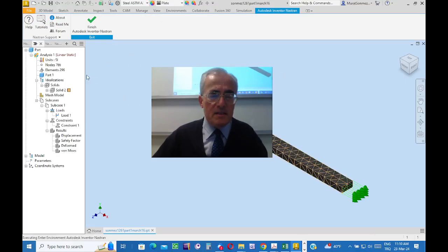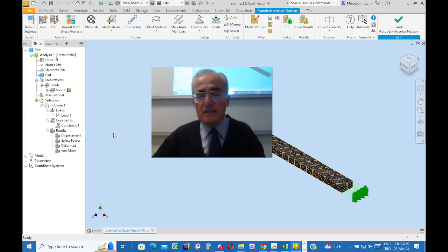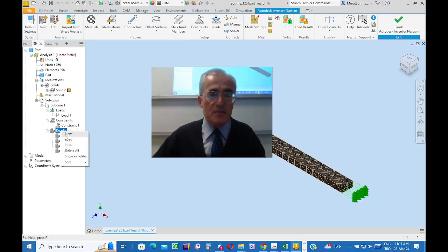And then, yes, similarly at the browser, we can find the icons. But if it is Nastran, then the results icon will be in a ghost, lighter tone, where the results are not ready to have a look at. Well, you need to load the results. Either bring the cursor onto the results icon, right click the mouse and select load, or equivalently click on the load results button. Okay, whichever you like.